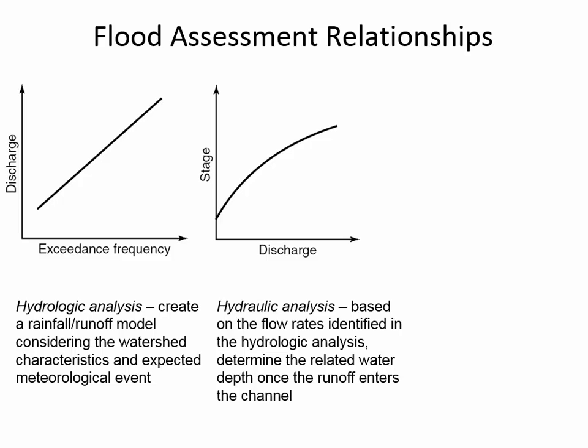And the reason why it matters, the stage, they call that stage, how deep is the water, is because maybe at a certain depth, here's the house. And so the hydraulic designer is going to find out how big of a storm. Does it take a 100-year storm before the water level gets to the house? Does it take a 200-year storm before the water level gets to the house? That's the question that is coming up so far in the analysis.